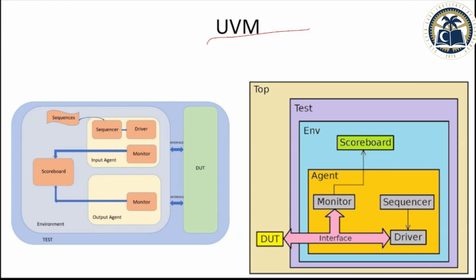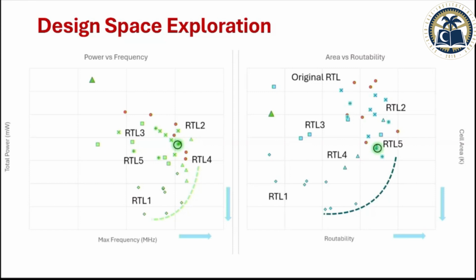And the other one is that UVM is a framework where you have a simulator already embedded into your verification code, and you are testing the code. Because of the importance of everything I have mentioned, there is a framework. And as I mentioned earlier, there is also a semester level course where they learn more about UVM. But I know for sure that you can just generate this UVM code. I've generated it myself, you generate that UVM test bench, and then just plug your design specific information into UVM to make it work. So we will do that at some part of the course.